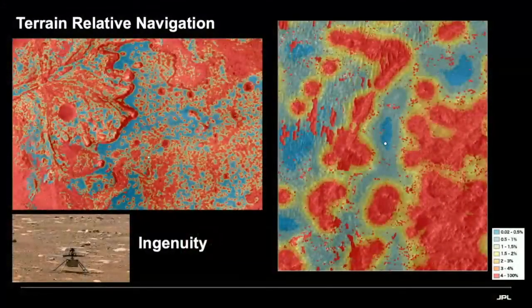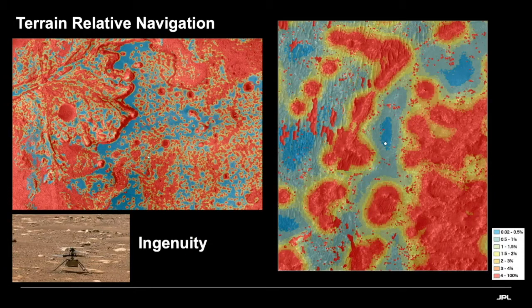And we had some cameras on board, and they took, autonomously, images of the surface, and it mapped the features in those images to our map. And as we descended on the parachute, it got a measure of the velocity as it's moving over those features. So it knew where it was, and it knew where it was traveling, velocity-wise, and it found the closest safe zone. And then on board, it did a propulsive maneuver called a divert maneuver to move to that safe zone.